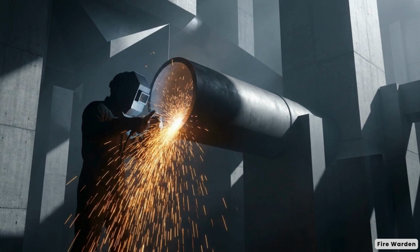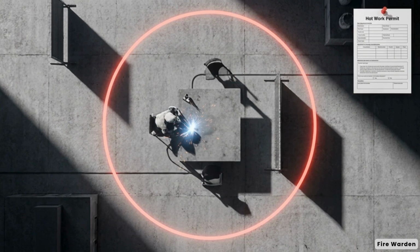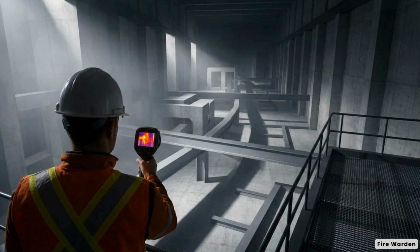Hot work, operations like welding, cutting, and brazing, introduces a high-energy ignition source into your environment by design. That level of energy demands strict geographical isolation. This top-down blueprint highlights the mandatory 35-foot circular safe zone that must be established around a welding station before a permit is issued. Even after the work stops, a dedicated fire watch must remain on site to monitor the area for latent, delayed smoldering that might surface hours later.